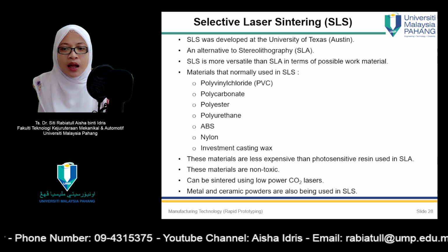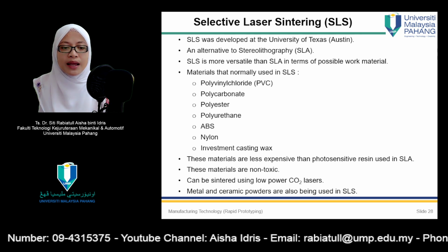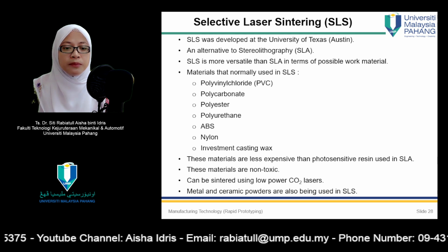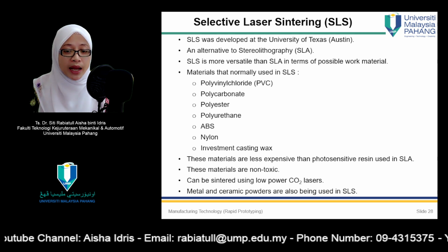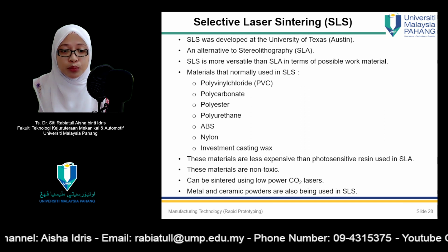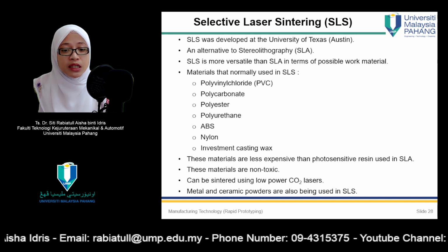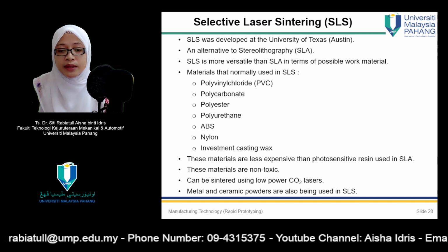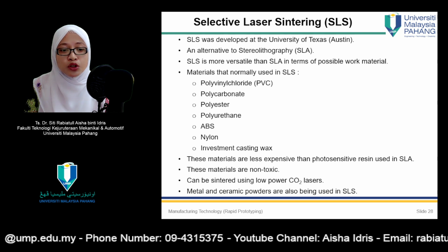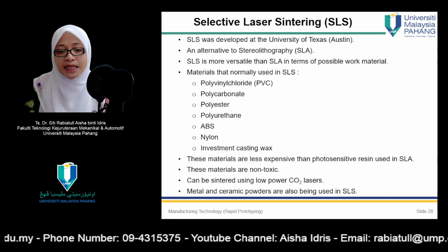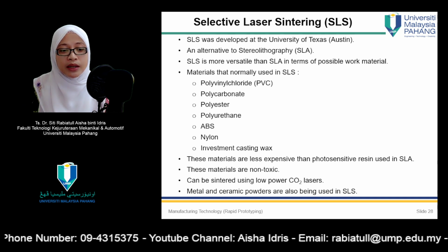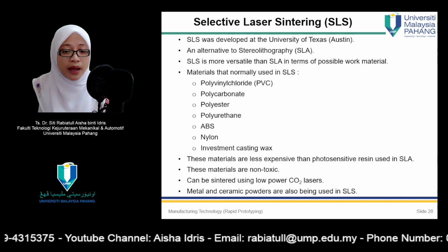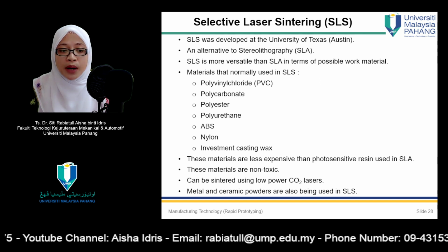Selective laser sintering, or SLS, uses a moving laser beam to sinter heat-fusible powders in areas corresponding to the CAD geometry model, one layer at a time, to build a solid part. After each layer is completed, a new layer of loose powder is spread across the surface using a counter-rotating roller. The powders are preheated to just below their melting point to facilitate bonding and reduce distortion. Layer by layer, these powders are gradually bonded into a solid mass that forms the 3D part geometry.